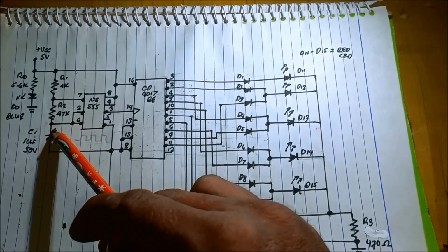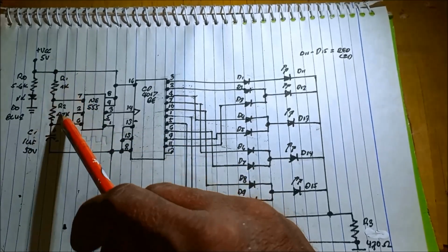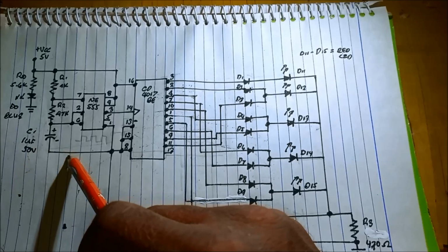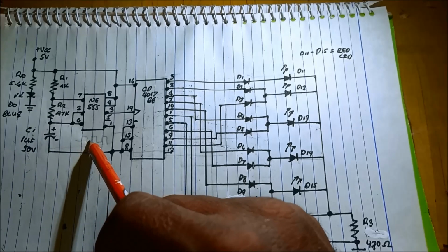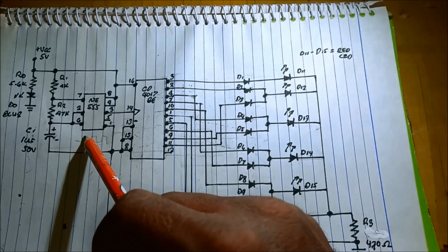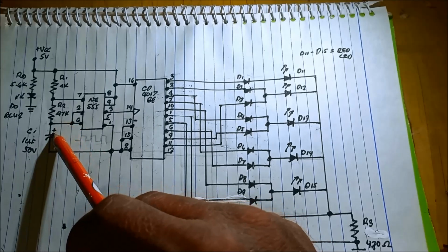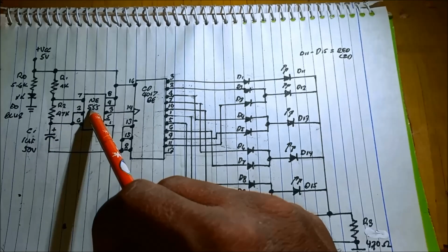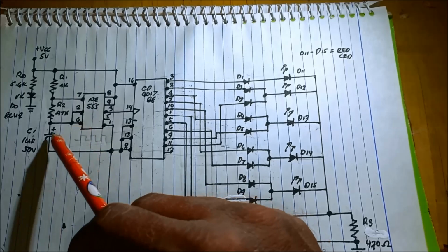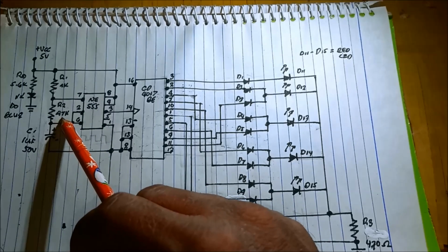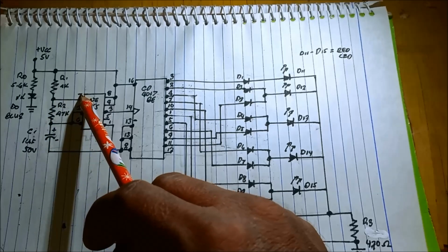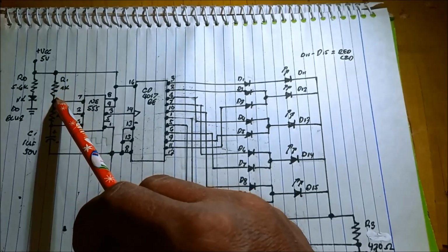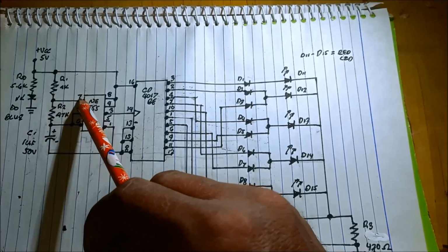It is due to the charging and then discharging. When the capacitor is charging through 5 volts, R1, R2, and then to the capacitor, 1 microfarad 50 volts, it will produce a positive pulse. And when it is discharging through the trigger and threshold pins, and then also to pin number 7, the discharge pin, and then R1, current flows into pin number 7.